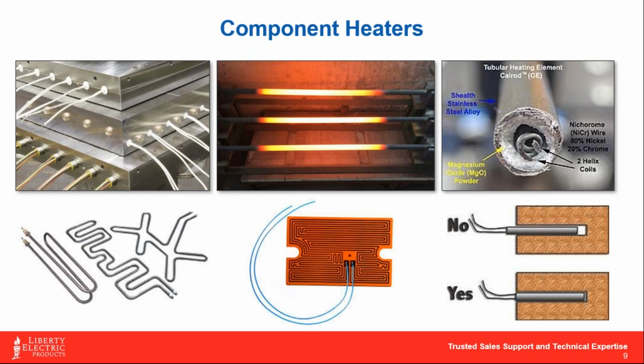The upper left-hand picture is a heated plenum. I like that picture in particular because you see all the leads coming off for some of those heaters. Well, the silver stubs that are in between each of those leads are cartridge heaters coming back in the other direction. So here's an application where they put a lot of heat into this plenum. It's usually used in something like rubber or plastics forming, where you've got a hot metal press that's coming down and forming a piece of material or fusing it. But this is an example where it may have a high heat requirement, where there's that many heaters, so they want a really fast warm-up time for their system.